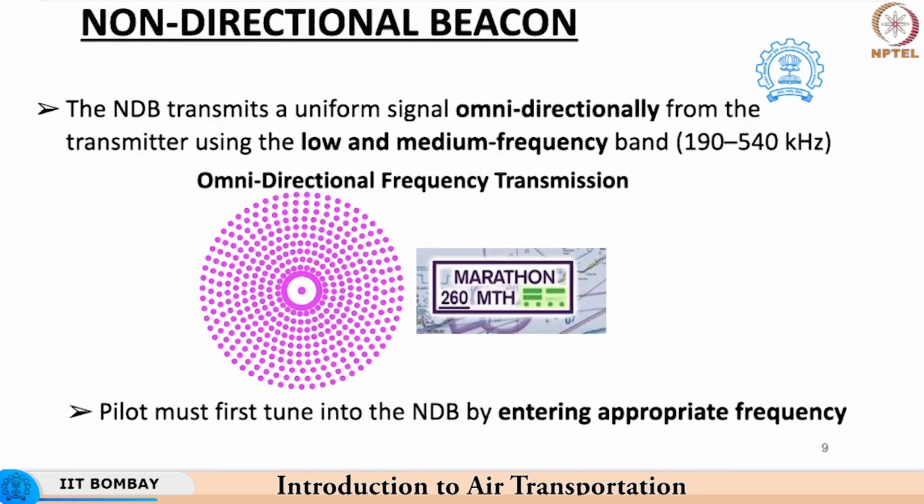So for example, in this particular figure, this marathon basically explains the fact that this navigation aid is named Marathon, and it operates on a frequency of 260 kilohertz. Hence, while carrying out the navigation in flight, the pilot needs to tune his receiver to this particular frequency to carry out the navigation.